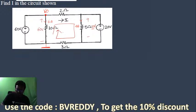Fine. Now this current is 6 amperes here. We need to get this current, we should get the I value. What we can do here, this is another node. We don't know how much this voltage is here. Yes or no? This is another node. Let us call this node voltage V, let us assume.